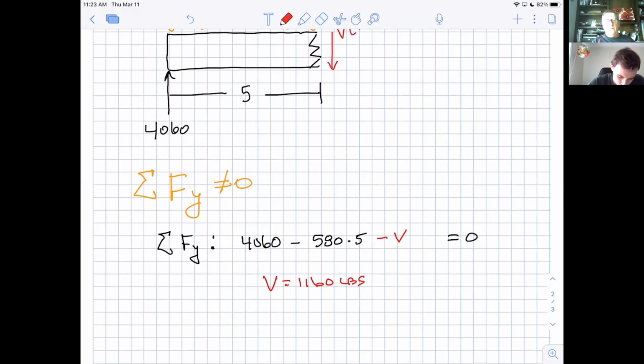That means that at 5 feet in, that beam better be capable of resisting, and think of it as one hand up here pushing down and one pushing up. If it's trying to go like this, does it make sense that if you pushed with 1,160 pounds of force, that beam better not slice in half, otherwise it's going to actually fall? Do you see what I'm saying?